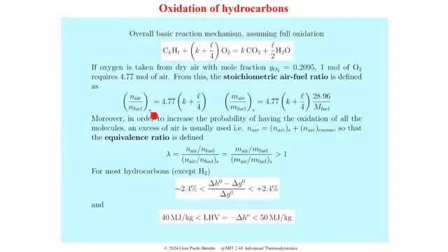The S stands for stoichiometric. If you are more interested in weight fractions, this is the air-to-fuel ratio, mass-wise. So you have to multiply by the molecular weight of air and divide by the molecular weight of the fuel.